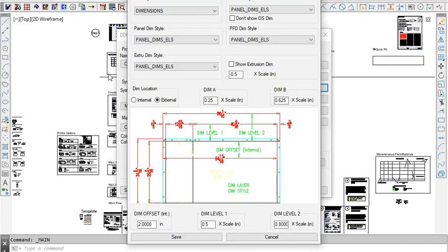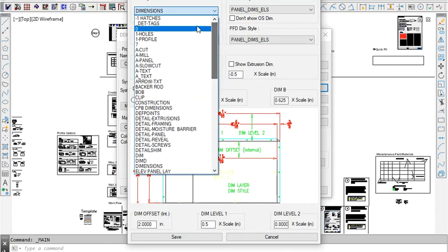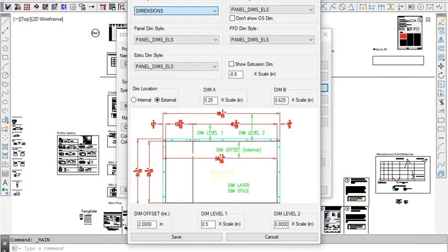If for some reason you forget to put the template in there, when you run the program, for example, maybe the dimensions layer doesn't exist in this architectural drawing. So the program would default to the very first dimension, very first layer in this thing. Same with the dimension style. So it's kind of key on your part to make sure you follow suit here and put the template in there. I'm just saying, you should have a template today anyways. So these are your settings for that.